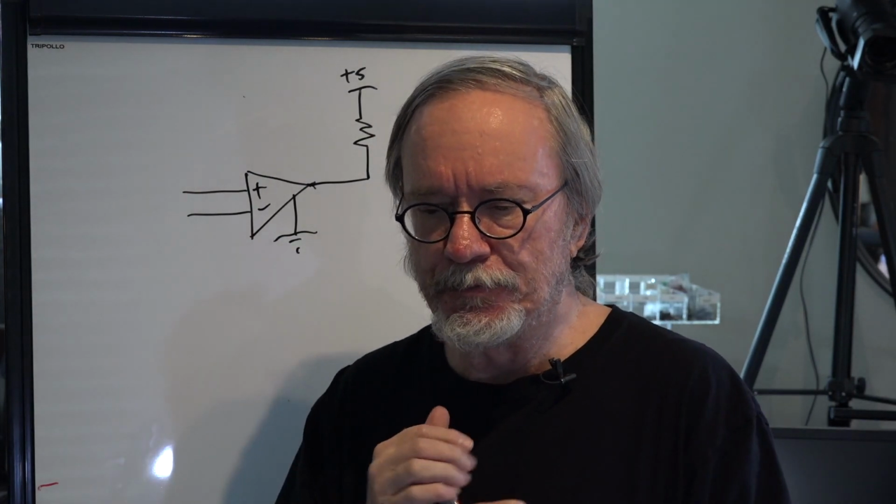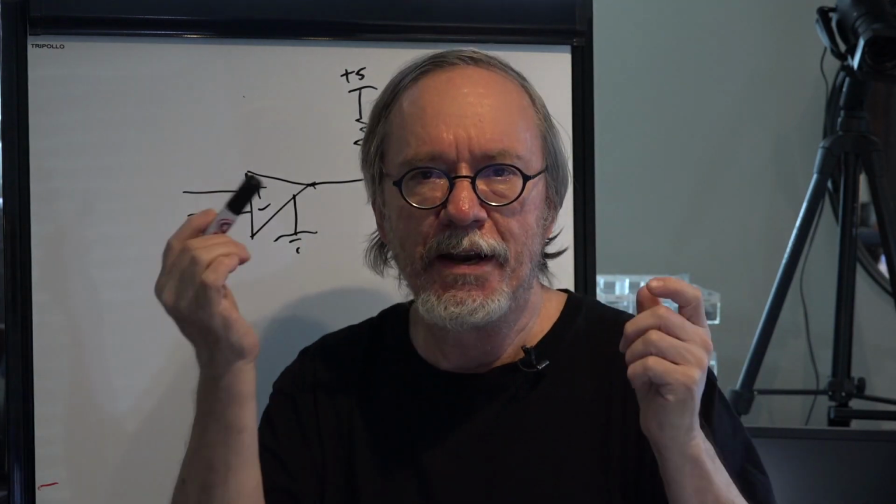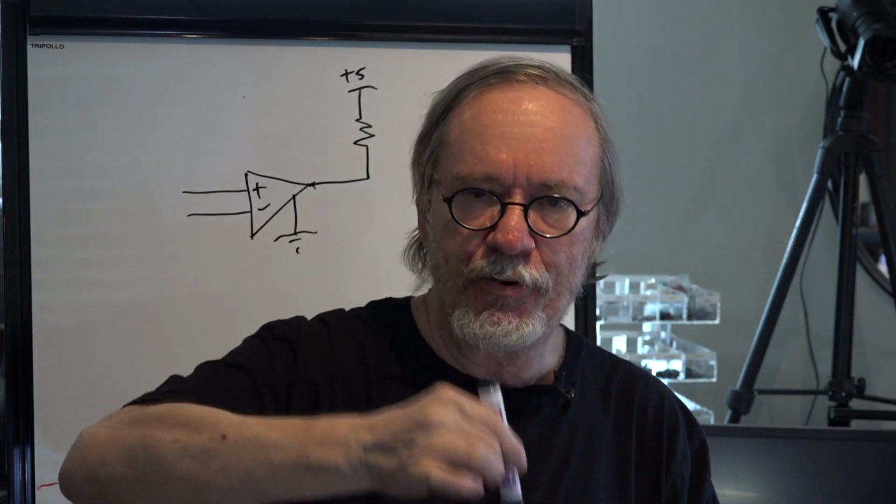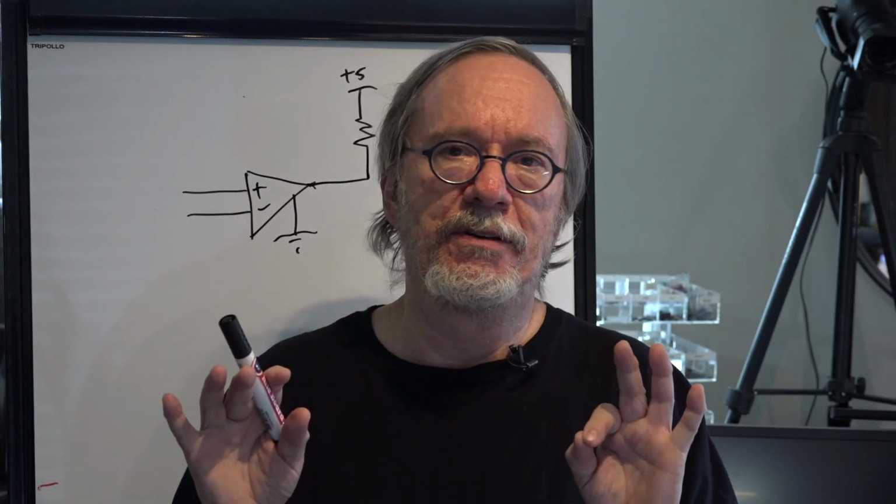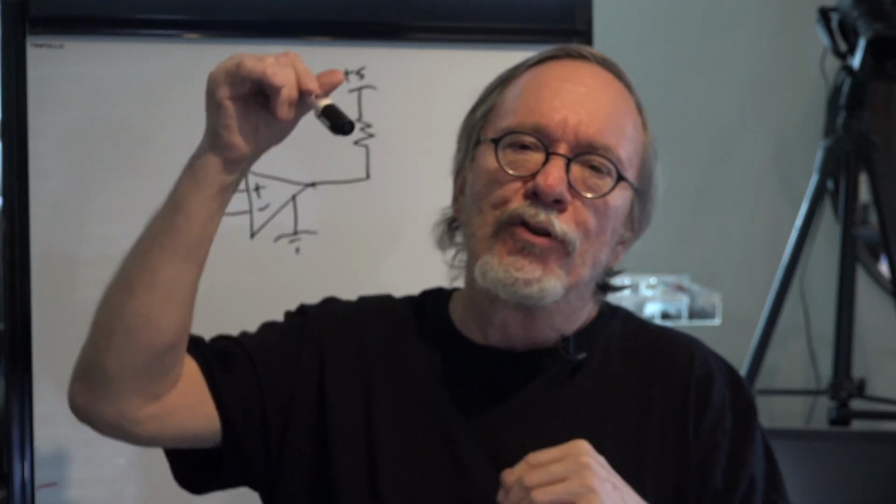And I'll give you an example. I've got a scope and a scope probe. And I put that probe down in and I see things. I want it to be as though it's not there at all. Don't you be messing with it. No Heisenberg, stop. I want the probe to go down and be as though it's not there. I want you to sample. I want you to tell me what's going on, but don't change anything. What's it like if you weren't there, type of thing.